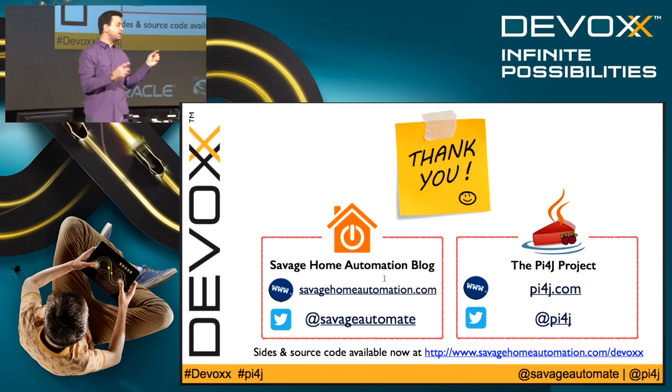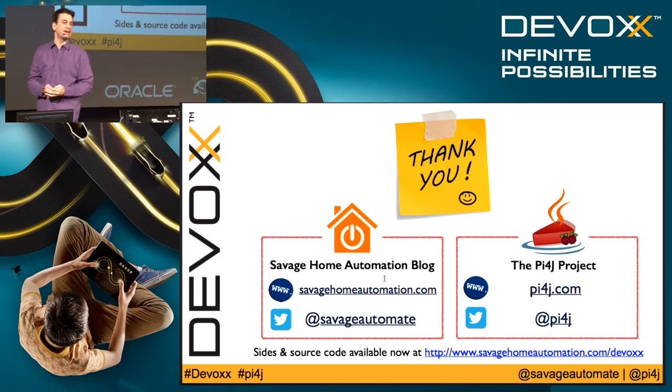In the Pi4J programming logic, it still looks like GPIO pins, but it's really going across a data interface to another peripheral circuit board. So that's one option to expand your capability. Or look at the higher capacity models. The compute module supports 46 pins. So a little more expensive, but you have greater capacity.